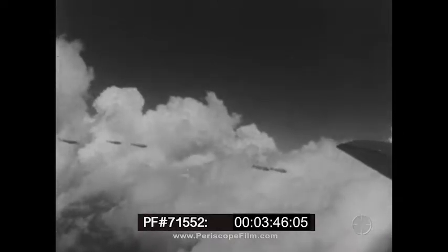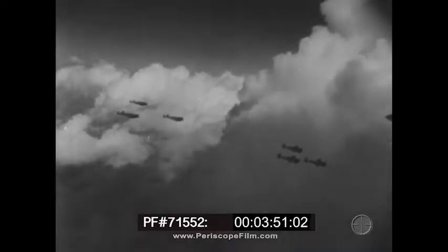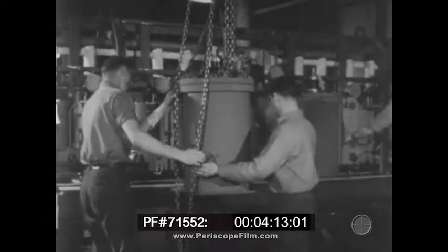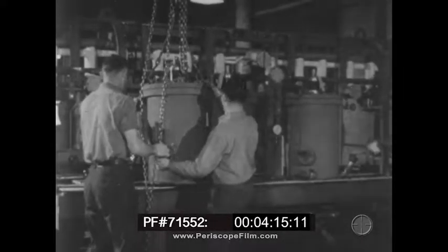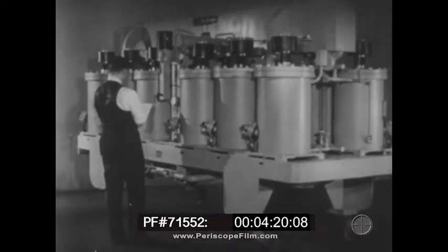Electronic rectification is also helping to build American airpower by making available record-breaking quantities of aluminum for plane construction. From Arkansas mud to American airpower involves a complicated conversion of material. Before pure aluminum can be extracted from this bauxite ore, direct current must be applied in a vital reduction process. To obtain that direct current from AC transmission lines, the ignitron rectifier is used. This Westinghouse electronic device changes vast quantities of AC to DC with higher efficiency than similar type of conversion equipment.